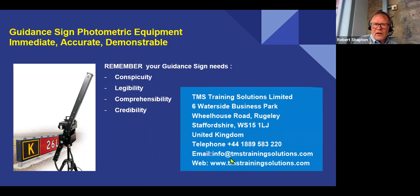The signs fade, the fascias fade tremendously. This is not an acceptable excuse for non-compliance. You have to replace them. And in particular, I would point out that we've been testing some of these where they're doing an LED upgrade and not changing the fascia, and they're non-compliant when they've been upgraded.